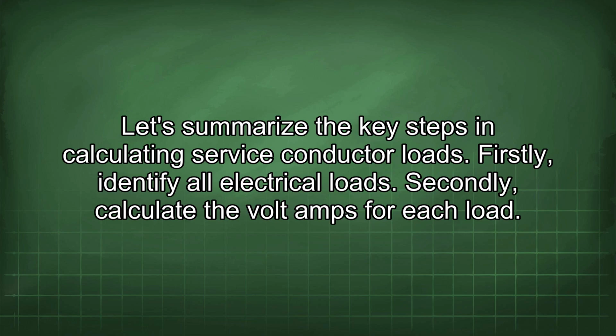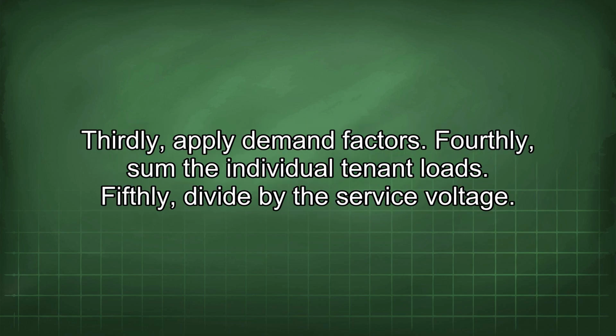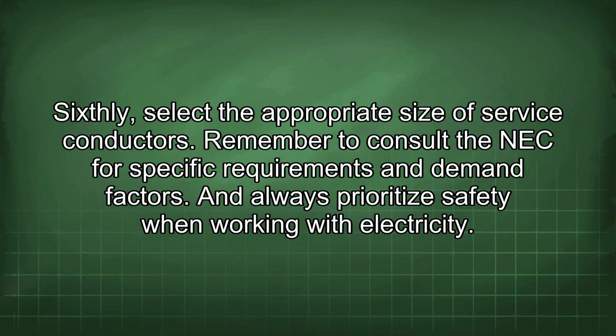Let's summarize the key steps in calculating service conductor loads. Firstly, identify all electrical loads. Secondly, calculate the volt amps for each load. Thirdly, apply demand factors. Fourthly, sum the individual tenant loads. Fifthly, divide by the service voltage. Sixthly, select the appropriate size of service conductors.